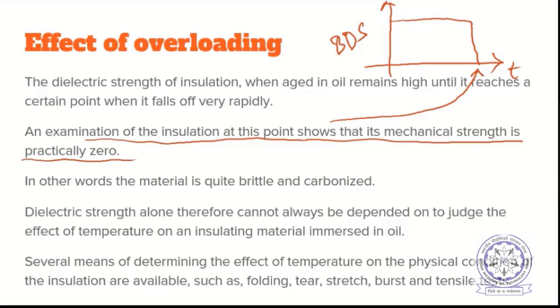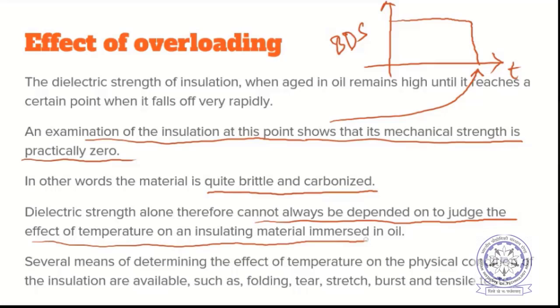In other words, the material is actually quite brittle and also carbonized. So oxidation took place and then the material has carbonized. So dielectric strength alone cannot always be depended on to judge the effect of temperature on insulating material immersed in oil. So this is one problem. We cannot rely on breakdown strength alone because the material has already lost mechanical strength. So the breakdown occurs suddenly here.